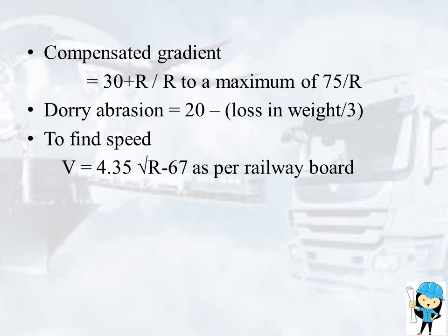Compensated gradient, which is equal to 30 plus R divided by R, to a maximum of 75 divided by R. So the compensated gradient value is among the most frequently asked questions in several competitive exams. So it is very important to know the formula of compensated gradient.